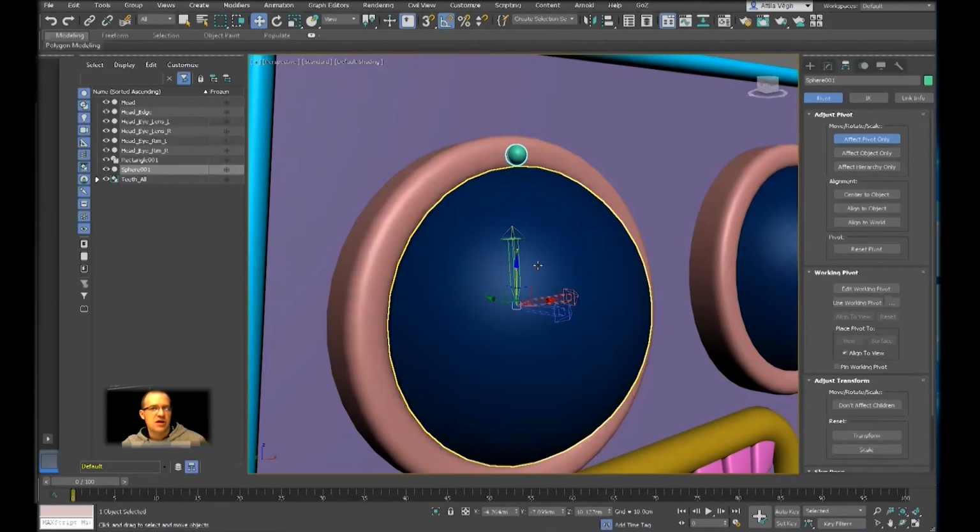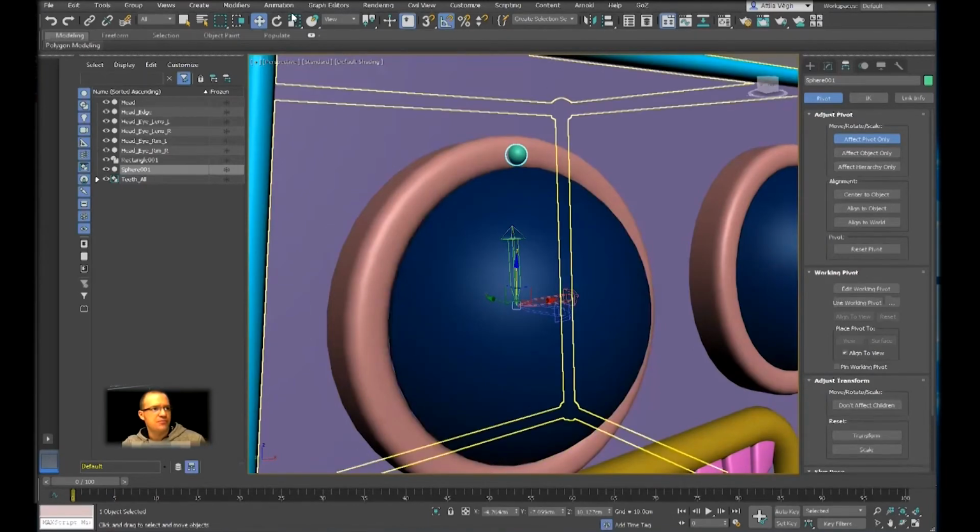How to do it? Please take a look at the top row in the menu, and under the menu there's this toolbar, and in the toolbar, right beside the mirror, we have align. But align is complex. We have different ways to align things. Right now, we want to make it as simple as possible, so we will use the quick align. The quick align is not the default tool. Can you see the tiny triangle in the bottom corner of this button? That tells us we have more.